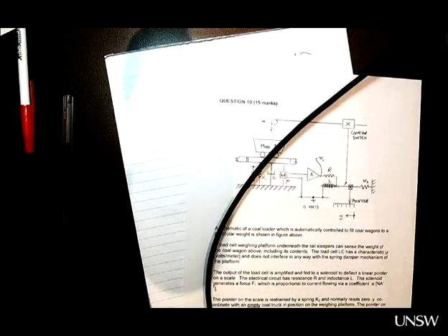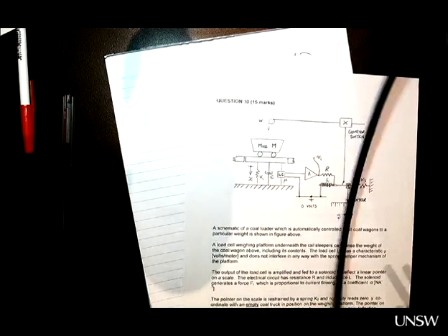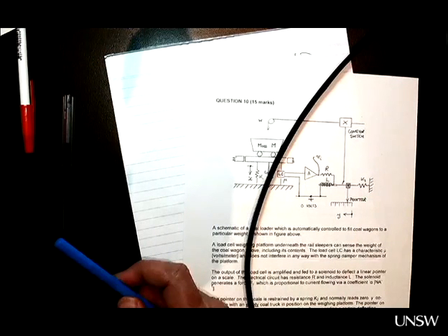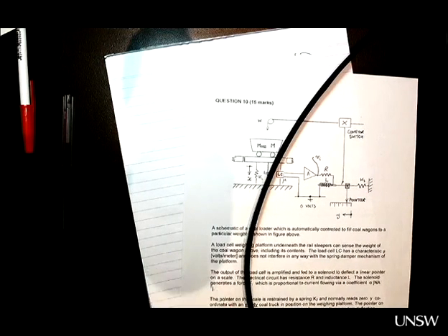I'm just wondering what would happen for the second order system if you didn't have a double loop. Then you have two time constants. And what does that mean? In a system, that means the longer time constant dominates the response.